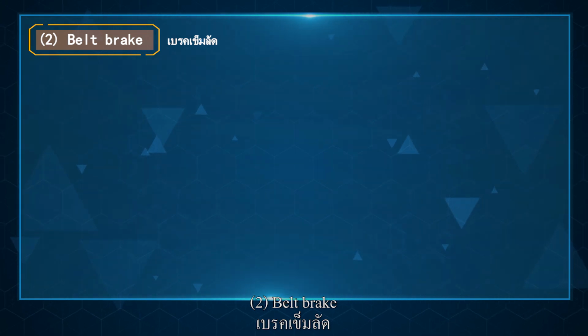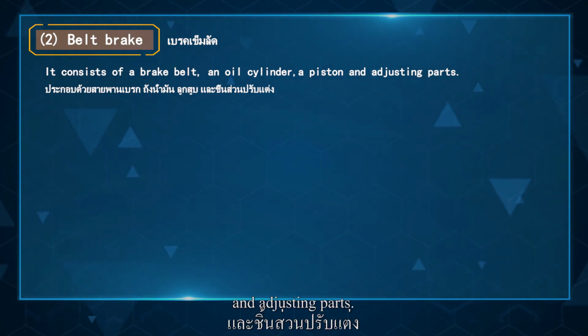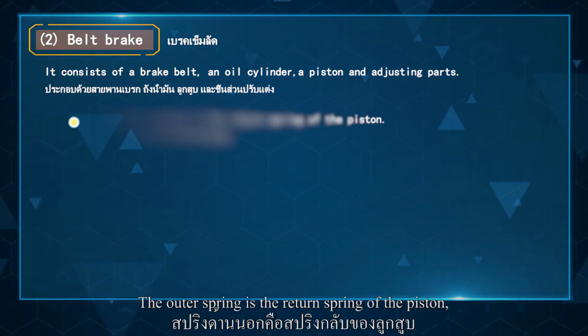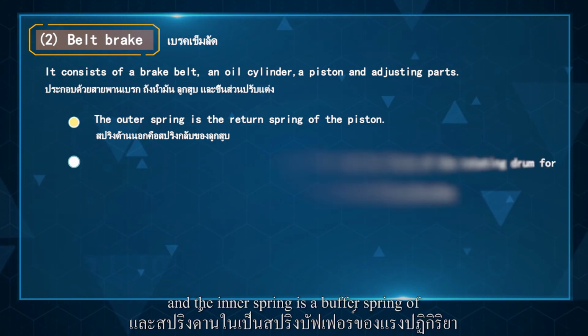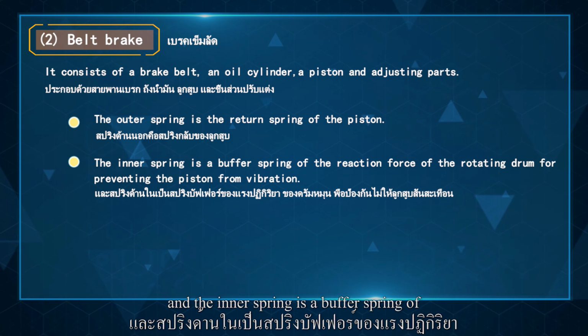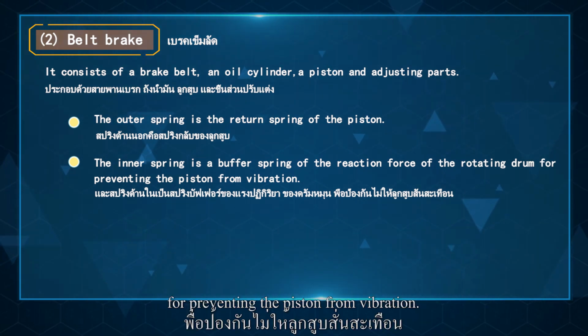2. Belt brake. It consists of a brake belt, an oil cylinder, a piston, and adjusting parts. The outer spring is the return spring of the piston, and the inner spring is a buffer spring of the reaction force of the rotating drum for preventing the piston from vibration.